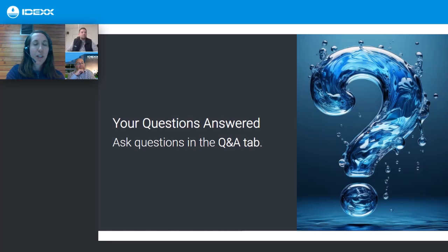So we prefer to be backwashing on a set time. And if we're starting to see that we're having to backwash the filters on head loss, then we want to bring that time back and actually backwash them on a frequency. It helps us to manage also our backwashing systems. So we don't want all our filters to kind of queue up at once, and then we've not got space in the wash water tanks. We want to be able to plan for it ahead.